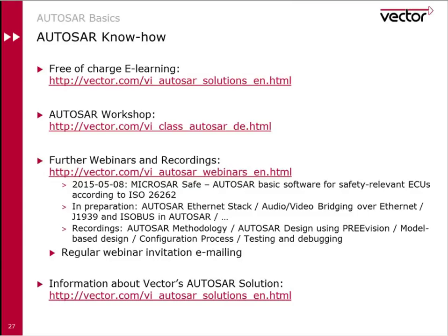The system description is the file describing all the communication, the dependencies for the whole vehicle. So therefore, the vehicle manufacturer should provide a system description. Till now, not all vehicle manufacturers provide the system descriptions, but more and more will do. They provide typically an ECU extract of the system description, so just focused on your personal ECU then. And for sure, also many vehicle manufacturers provide legacy files like DBC, FIBEX, or LDF files.